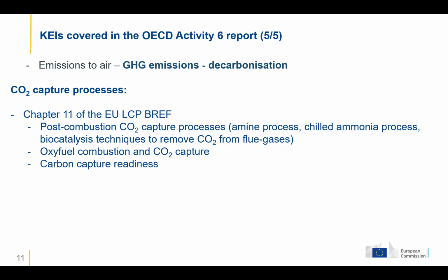Here there are no BATs, no best available techniques about decarbonization in the EU BREF, but chapter 11 of the LCP BREF, which is about emerging techniques, has quite an extensive reference to CO2 capture processes, mainly post-combustion carbon dioxide capture processes, and there is a description of the amine process, the chilled ammonia process, and biocatalysis techniques to remove CO2 from the flue gases.